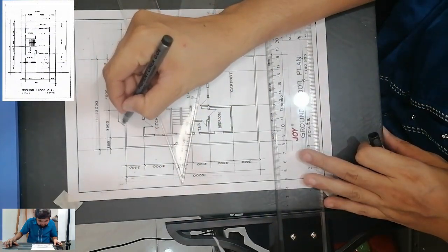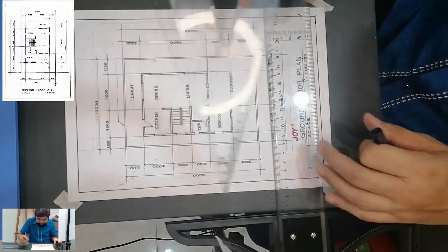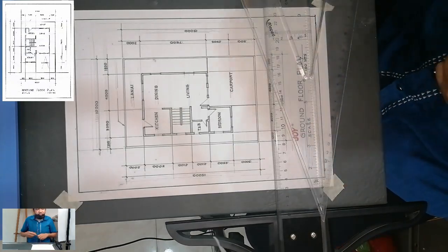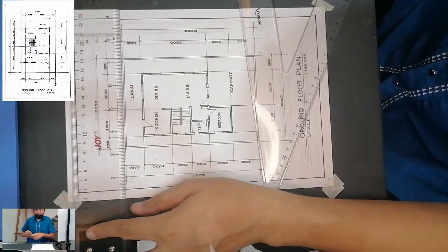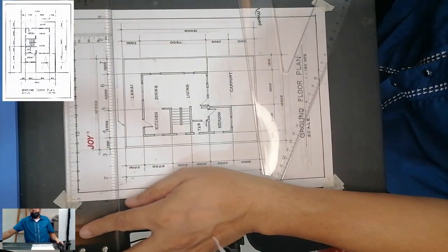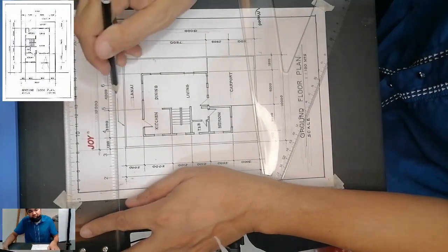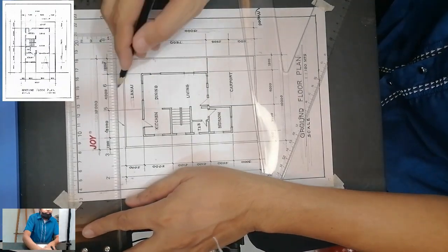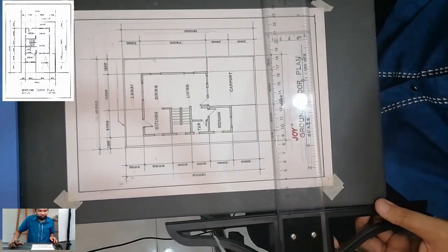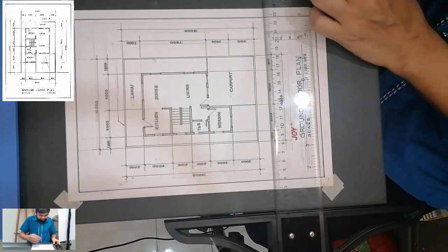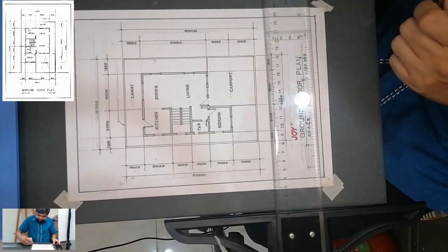So we use a thin tech pen, and for the letters, we would normally use a pencil first for the draft of the property line. Again, a good draftsman never letters without a guideline. Even if it is a small letter, we will be using guidelines in lettering.